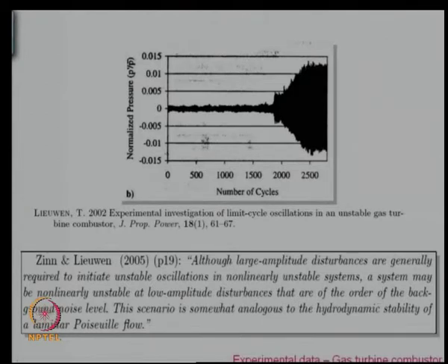This book was published in 2005, before we came up with this theory of non-normality, but he is talking about low amplitude disturbances. Generally triggering was perceived to be caused by high amplitude disturbances, but the people who did experiments noticed that you can see it at low amplitude disturbances. In hydrodynamic stability, this revolution happened in the 90s, perhaps starting in the late 80s; the battles happened in the 90s, and by 2000 maybe the people won the battle. There the non-linear terms are energy conserving, which means all the growth is because of a linear mechanism; the non-linear terms just redistribute the energy between the modes.